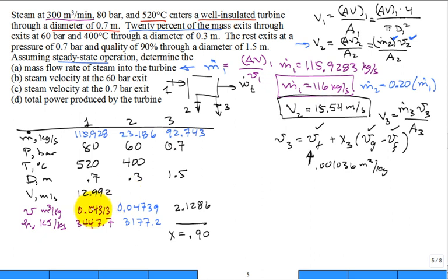Now just compare the other value, the specific volume at 2 and the specific volume at 1. Use your hands. State 3, every kilogram is occupying a much larger volume than it did at state 1 and state 2. If you have a calculator, just do the ratio. 2.1286 divided by 0.04313.